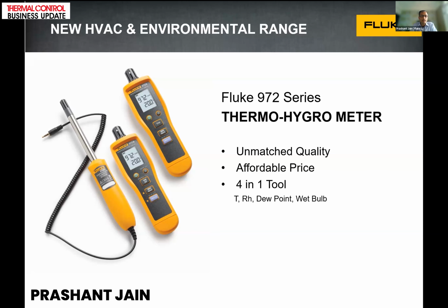While continuous monitoring gives us data, the problem is that the sensor is fixed at one place. So if I have a 5,000 square feet hall, my sensor will be fixed at one corner. The parameter may be dynamic. We have seen conditions where it was a data center and the sensor was placed very close to the air conditioning duct, and the sensor was always showing the right temperature and humidity, whereas at the far end of that large hall, the temperature was very different. Because we are getting the signal from the sensor, it was always saying the temperature was in the right condition, but at the far end of the server room, it was overheated and there was some problem.